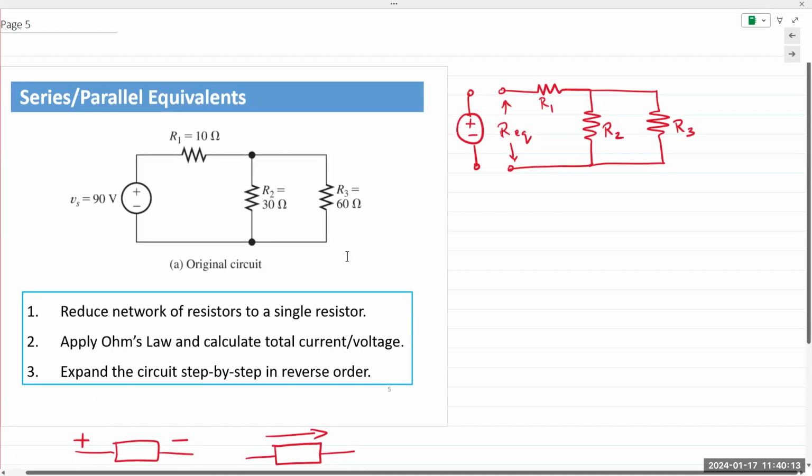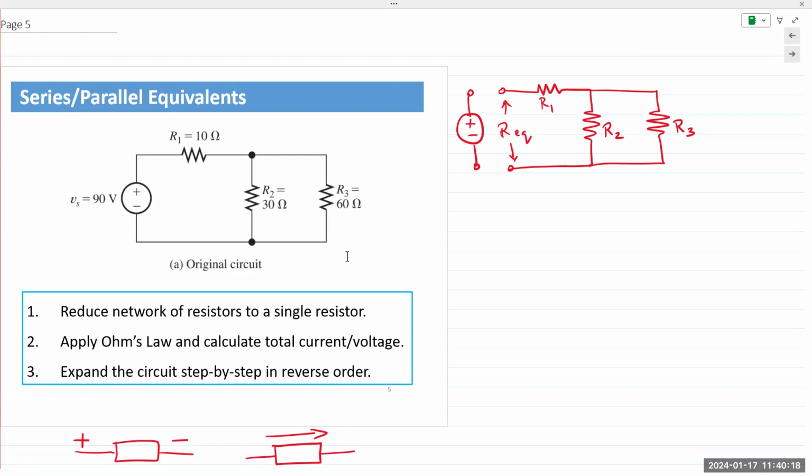We have voltage source Vs on the left. Polarity for the voltage is already given to us. Which direction is the current flowing for the source? Is it going up or is it going down? It's going up, minus to plus. So current goes up. I'm going to label that as I. If you are driving a car around the circuit, let's assume the current is a vehicle. You're driving forward, you're not going backwards, right?